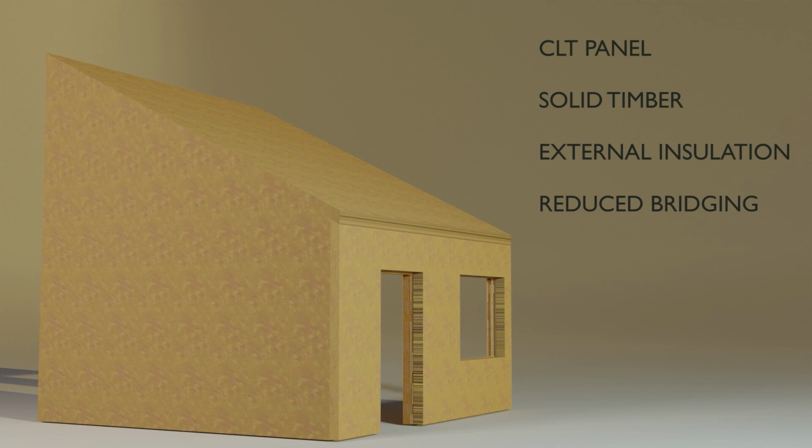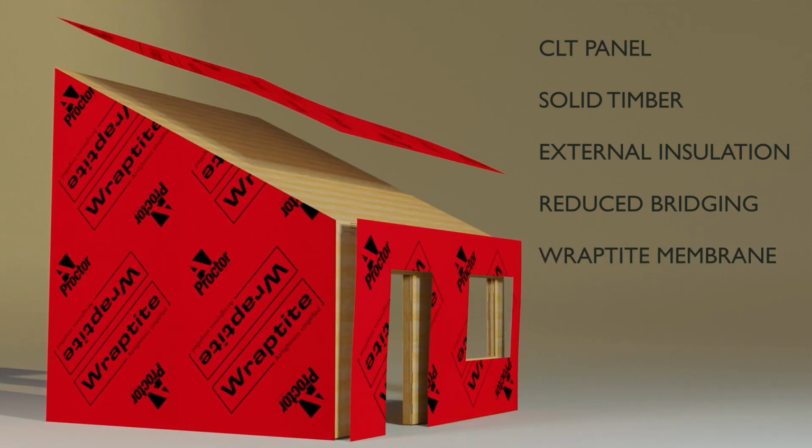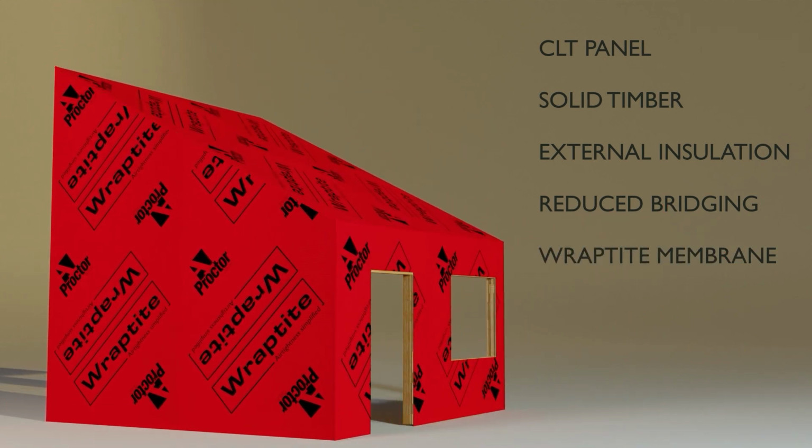This in turn means that other options are available for air leakage reduction, and this is where the Wraptite membrane is particularly useful. If we apply Wraptite externally over the face of the CLT panels, it will provide a degree of temporary weather protection during the transportation of the panels, or if applied on site to the building as a whole until the outer cladding is in place. This can allow work to progress internally as the space is mostly wind and watertight as soon as the membrane is applied, so temporary heating will be more effective and materials can be stored safely prior to installation.